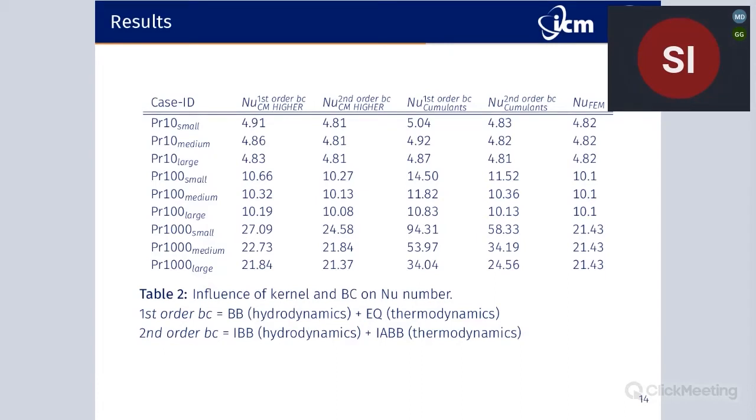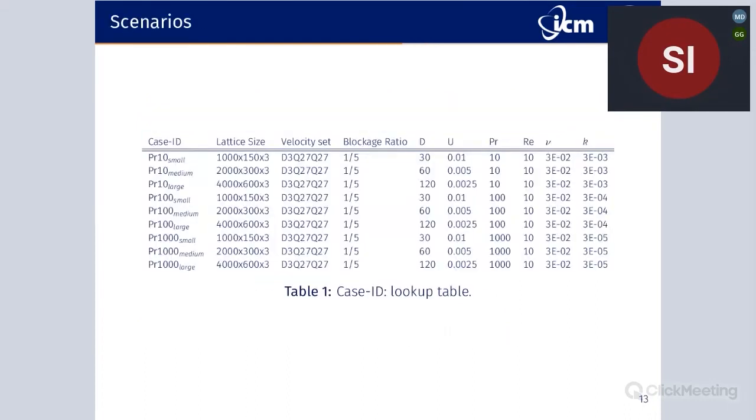And the mesh will need to be really, really large to give us valuable results. And the key point to take from this slide is to remember that the size of the mesh was like this. So this was about 7 million cells in the most difficult case. And later on, you will see how much memory and computational time is needed to solve such a case, and what we can do to alleviate it.